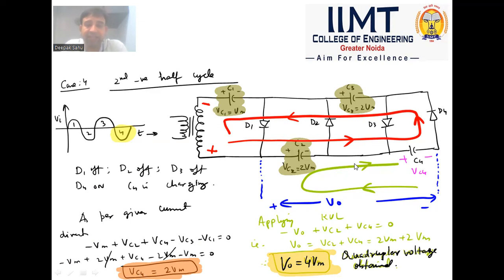But as the circuit suggests, using this circuit we can get thrice and 4 times the voltage on the secondary side. So we have to see how we obtain this, which is shown here in the green line. See this, the output here we have taken across C2 and C4. Now carefully watch. The voltage across C4 and C2 has been clearly matched with the output polarity. Otherwise, there will be cancellation in voltage values. So utilizing C2 and C4, we obtain the voltage V0, which is taken across capacitors C2 and C4, and this combination gives an output voltage of 4 times the basic supply.